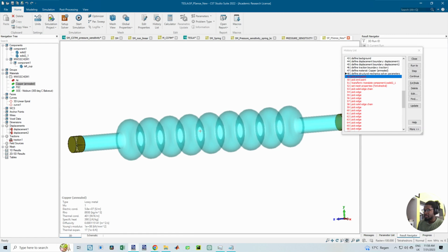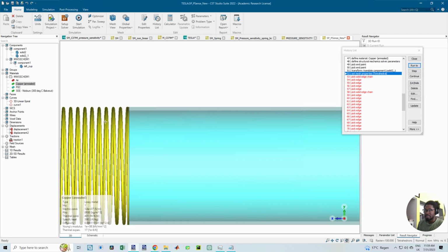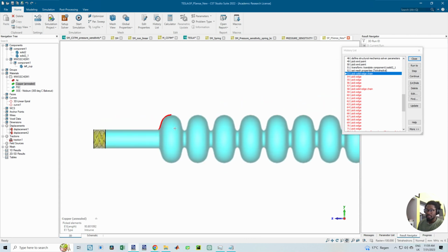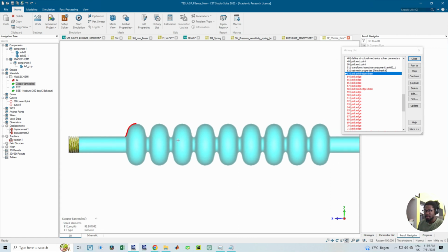So I tried meshing, and where I moved back this other spring that I mentioned that was overlapping, I corrected it here, and then you have no overlap again. And after the first run, I decided to do a little bit more post-processing, which is evaluating the displacement along the surface, the curve defined on the surface.